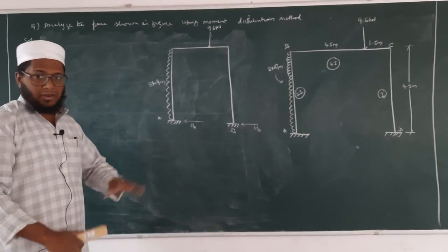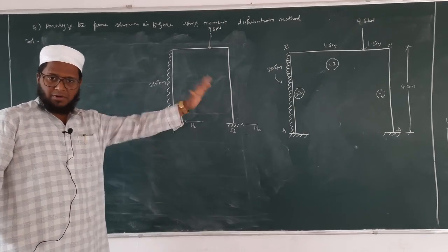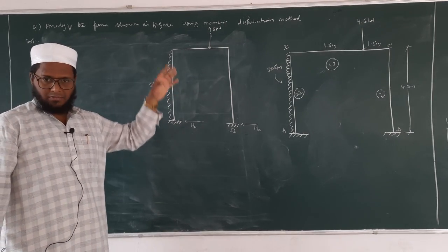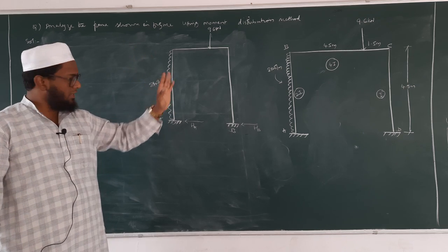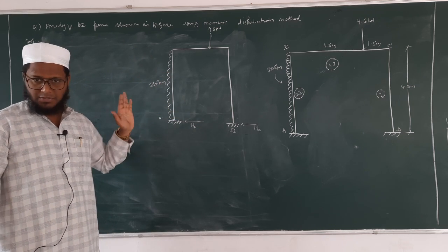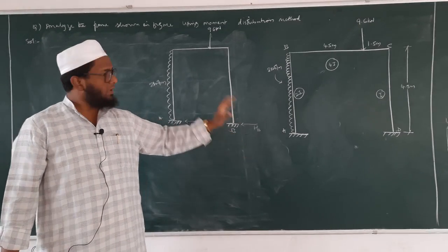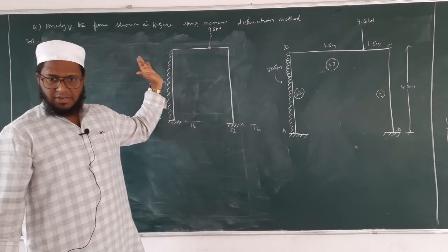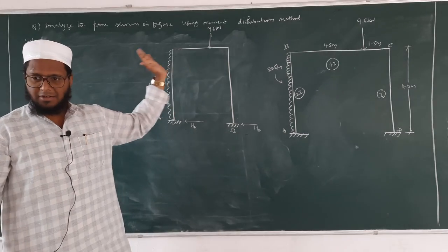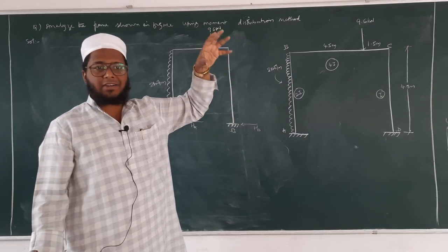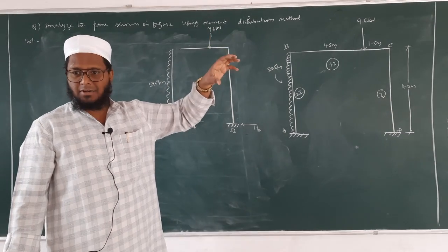Okay. We are not taking vertical reactions because we are bothered about the sway. Okay. Downward or upward direction reactions. We are bothered about horizontal forces now. Okay. Now we got reactions HA and HB. Okay. Now how the frame will get deflected? In this direction. To stop that deflection, what happens?